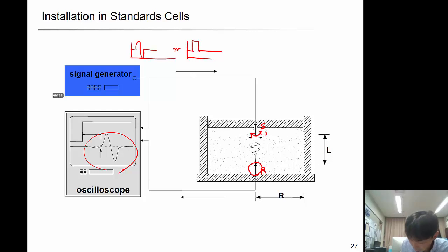There is also some P wave generated in this direction. This P wave can bounce back and reflect, and the reflected P wave can be captured in the receiver bend element. Or if the vibration is too much, the wave can go through the cap, the wall and the other bottom cap, and be captured in the receiver too. So there could be some other noise because of that kind of reflective wave.